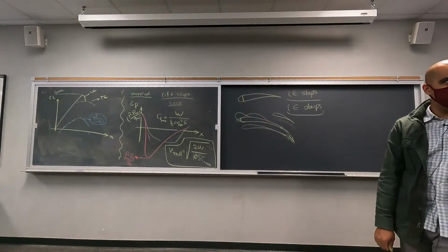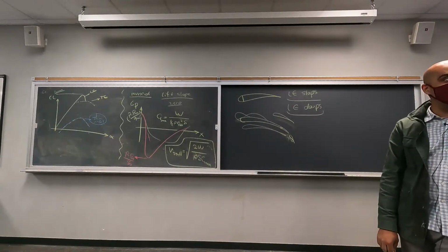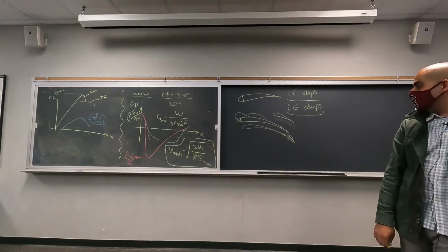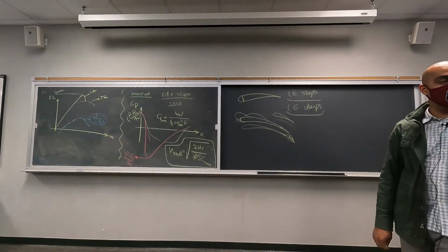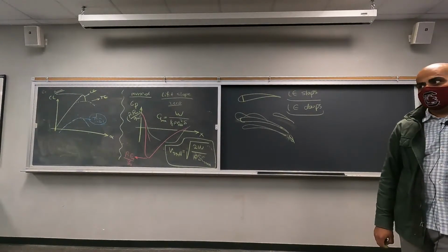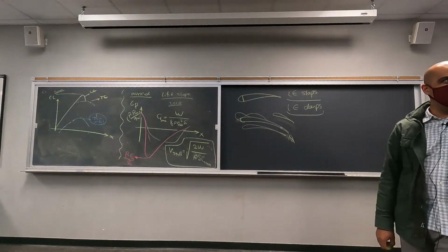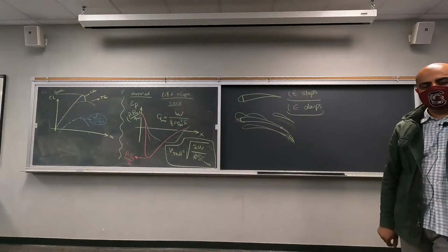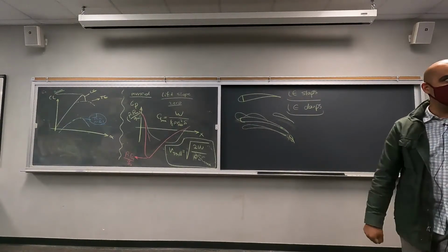What if you ionize the air towards the front of the wing and use magnetic fields to manipulate the flow velocity? Oh, that's a very creative way of looking at it. That's actually something they already do. It's called dielectric barrier discharges, right? So you are going to induce plasma on top of the airfoil, which is going to add a source term to the Navier-Stokes equation. So it is going to push the flow down.